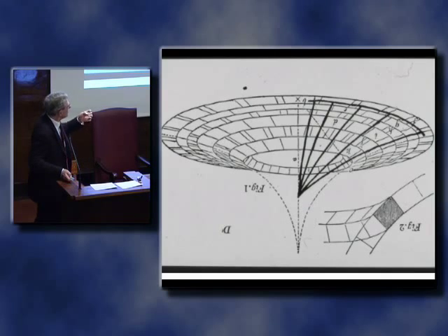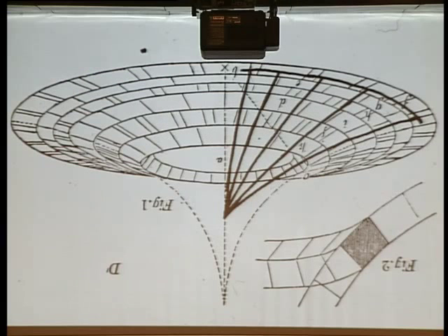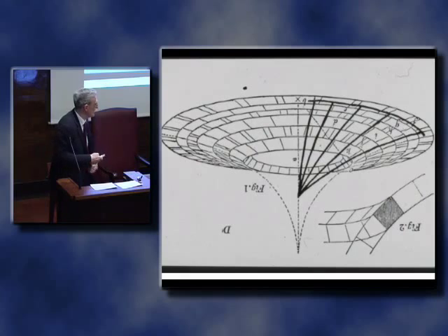And this does illustrate, actually, the second reason, I think, why fan vaults were abandoned. In building such a vault, the compressive forces along these lines build up and up. The equilibrium condition is inexorable. One must have compressive forces there, and they must come from somewhere.